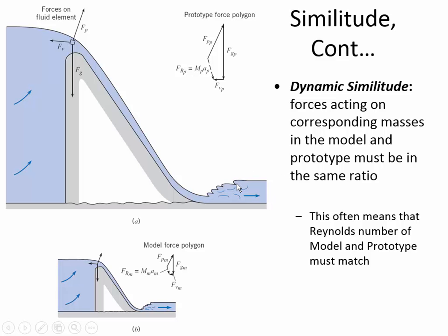This is a really important situation for hydraulic designers because the water is moving very fast at the end of the spillway because it's falling so far. And so there are a lot of physical models and computer models that are simulating this to try and find out what's the velocity of the liquid, and cavitation is an issue in spillways, and so they'll try and